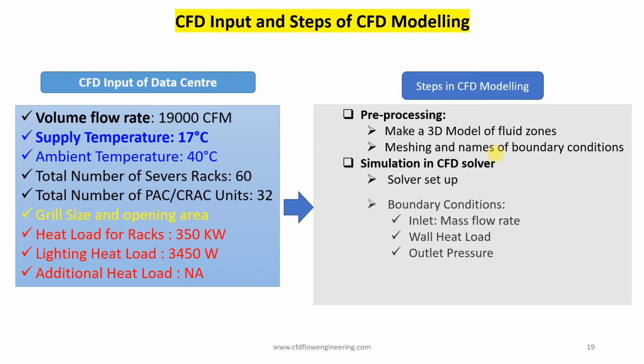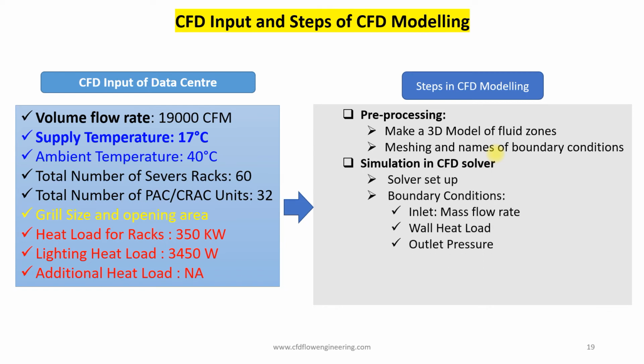The solver setup, boundary condition. Among boundary conditions, mass flow rate and inlet temperature of air are important. Wall heat load must be specified. Outlet pressure must be specified. The numerical scheme should be given properly.